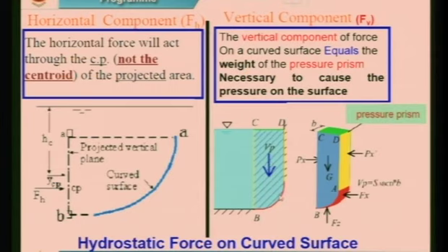So simple, you can see here, this is the curved portion of the gate and I have put a line B to C here and C to D here, and again it is joined to B. I have hatched it. You can see the hatching. Same thing you can see here also, it's a 3-dimensional view. B, C, D, A and B. So whatever the weight is there, that weight is nothing but the vertical component.